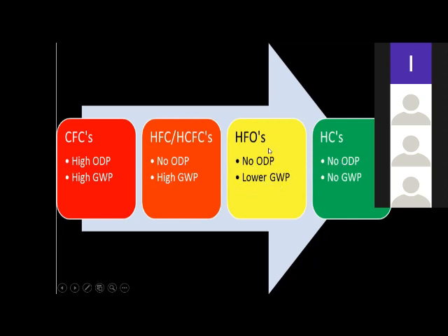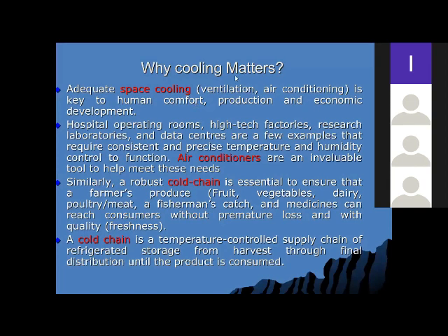Okay, and this is yellow, this is better. Hydrocarbons have no ODP and almost no GWP. So it's better that we can go for this. There are problems with hydrocarbons. They are flammable, and safety systems have to be there, especially in movable ones. Using these is sometimes difficult, so they have to have an innovative method of using this. So globally we are working on this. Locally also we have to adapt to these things in order to phase out HFCs and HCFCs.